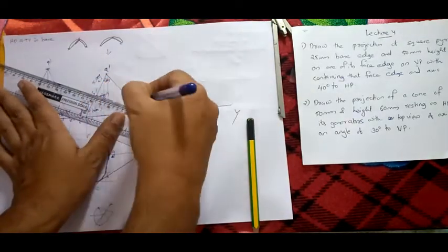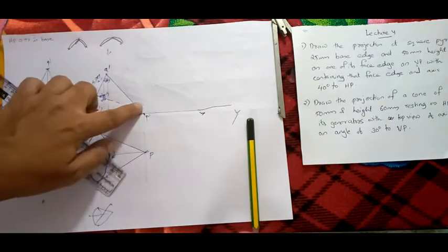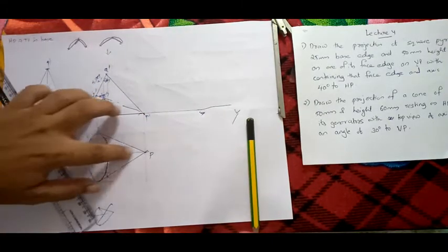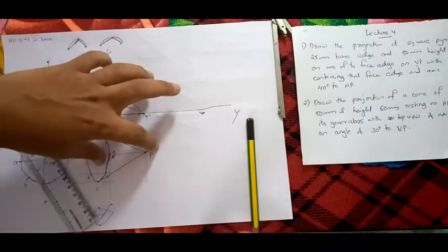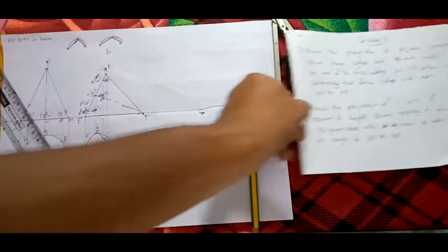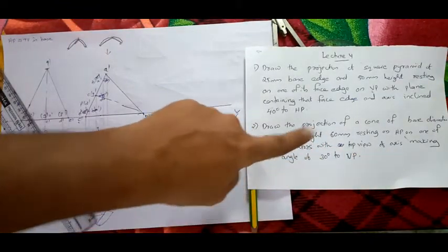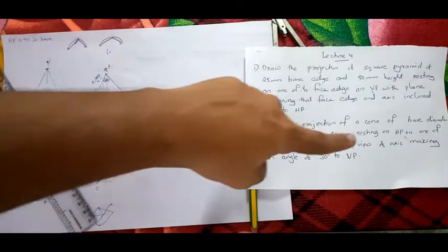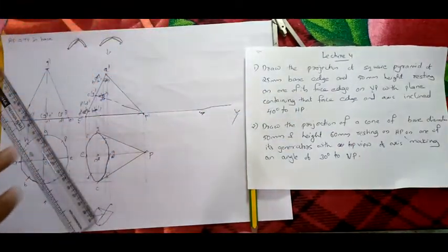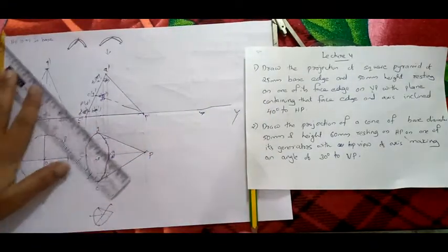I have drawn that. See, this is inclined, right? Inclined. True length with the true inclination. This is shortened length parallel to XY line. So this is shortened length, not the true length. So you cannot give true inclination here. So in the question they have given the top view is making. That means they have given the apparent inclination directly. If they had given true inclination, you would have to find the apparent inclination as we have seen in the previous video. But instead they have given the apparent inclination directly. So you can directly draw with the apparent inclination.